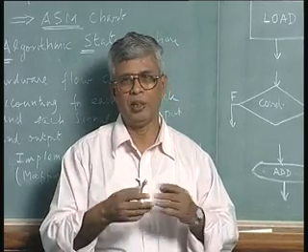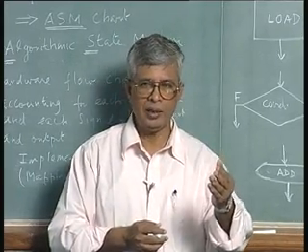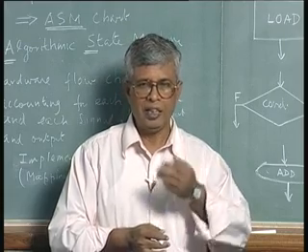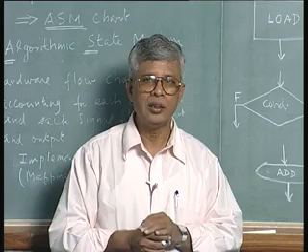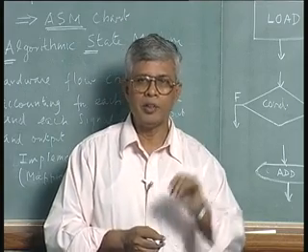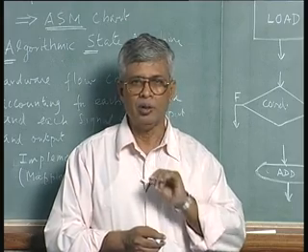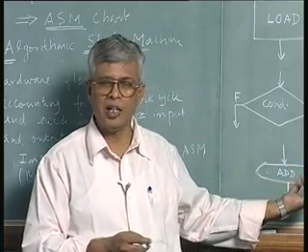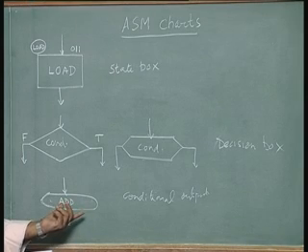It is an example of a multiplier. When you do a multiplication of two numbers, there is a multiplicand and a multiplier. For each multiplier bit, we add the multiplicand and shift if the multiplier bit is 1. Without adding, we shift if the multiplier bit is a 0. So that is a condition based on the multiplier bit being 1, we want to add, otherwise 0.